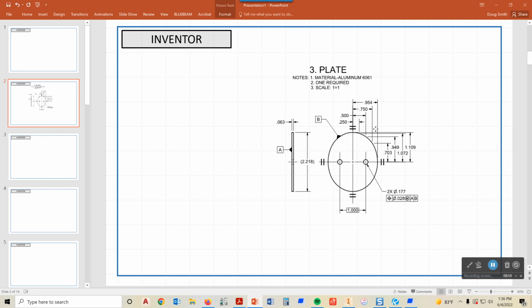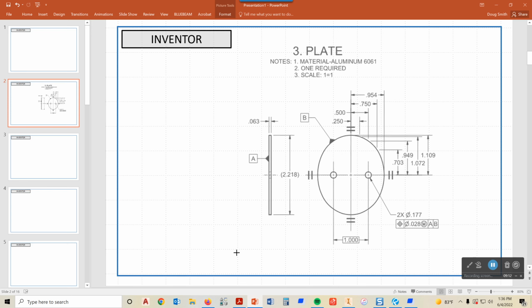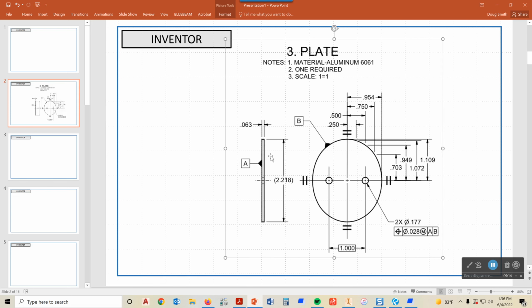You can still move that around, but I want to show you about sizing images. When you pick on an image, you'll see these grips that you get around the sides and in the corners. To size the image, always stretch from the corner, all right? And you can stretch from this corner here. Because the image overlaps but is behind the text box, it doesn't cover up the corner of the text box. What you don't want to do when you're changing the size of an image is grab it on the sides or on the top, and I'll show you why.